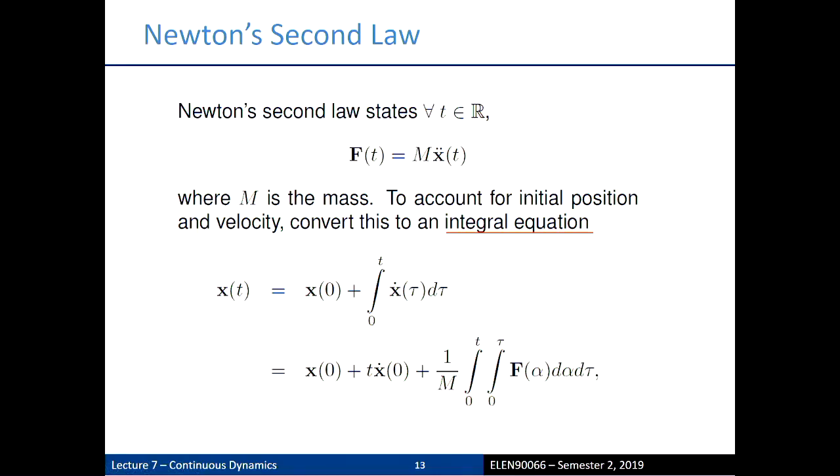Okay, and this is like the dead reckoning idea. So if we want to work out what the position is here, we have a double derivative. We need to do double integration. So we need to integrate this twice. We can convert our little equation into an integral equation to give us a position x at any time t, noting that x is in R3, okay? It's across 3 dimensions. And we've got dummy variables galore going on in here.